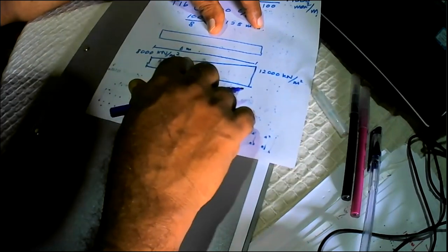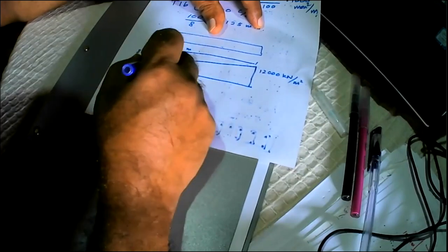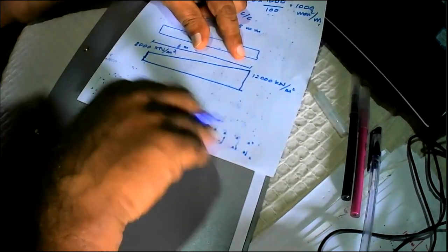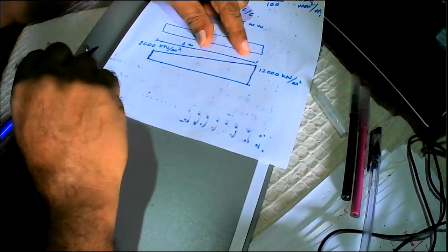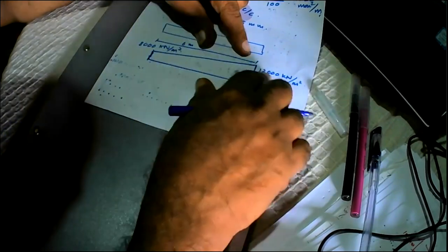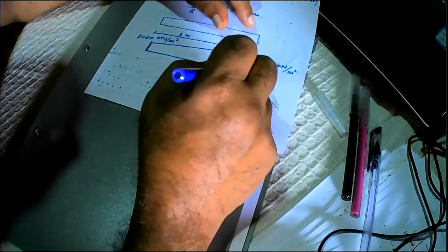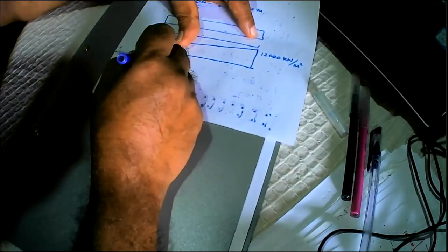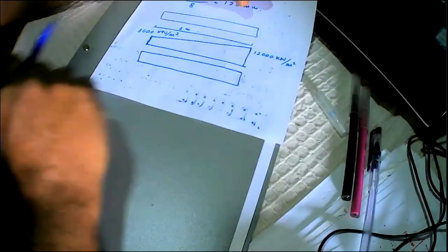So this minimum stress will be significant if you get tension here. But if you are getting compression, the minimum value is not very significant. But if you are going to get tension on this side, then the minimum value will be important. So if we get something like 12,000, then there's another way of finding the reinforcement, and this is applicable if the whole wall is in compression. Throughout the wall, it's in compression.